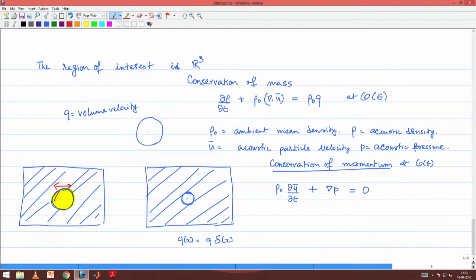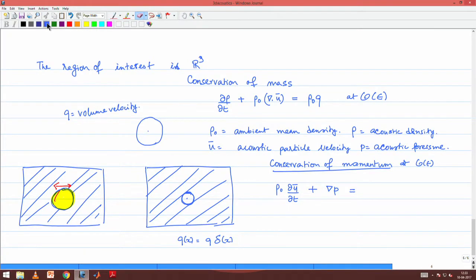So, around this point there is a force which is given from the external source to the fluid domain of interest, right. So, at this point precisely there is an imbalance of the momentum equation and you need to account for that, right. The imbalance of this momentum would now cause a right hand side to appear in this case, which I will denote as F. So, F is the force per unit volume, because everything here is per unit volume. F is the force per unit volume which is there within the fluid domain, because in the present picture we are not excluding the sources, we are including the sources. So, the effect of the sources would be to either create an imbalance in mass or an imbalance in the momentum laws, and this needs to be accommodated correctly in the equations of motion.